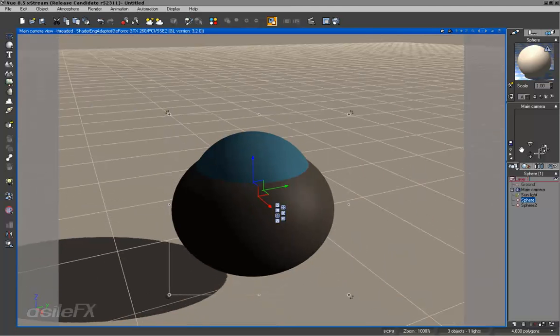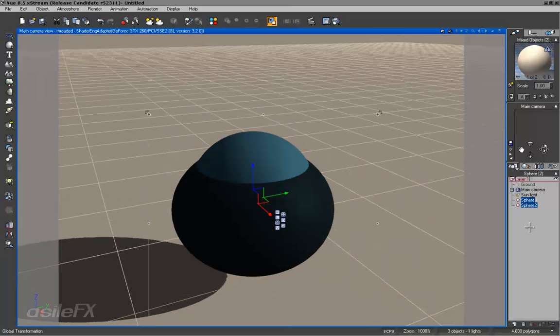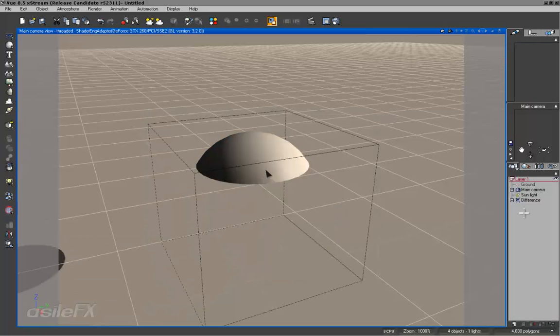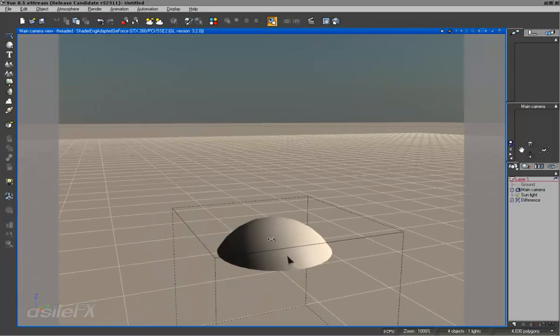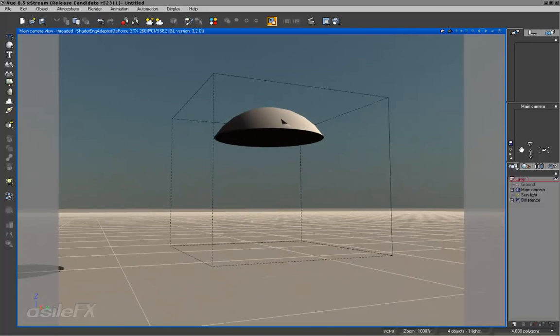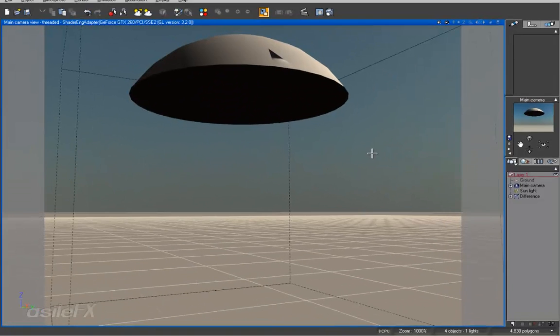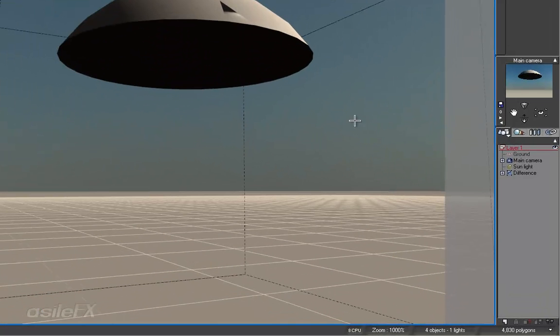And now we're going to set up a Boolean object. So select the cap first, then the fin object, go over to the left, and we can use a Boolean Difference, and that's going to subtract one object from the other and cut it out. So this is another way that can be useful for just piecing the objects together as separate objects.